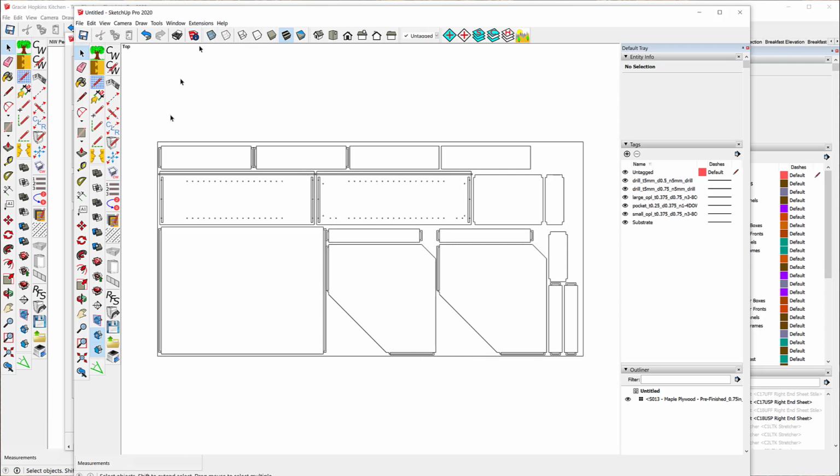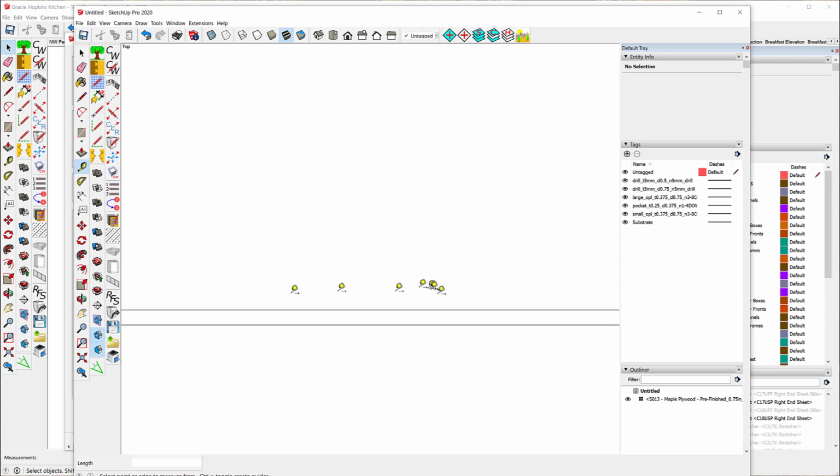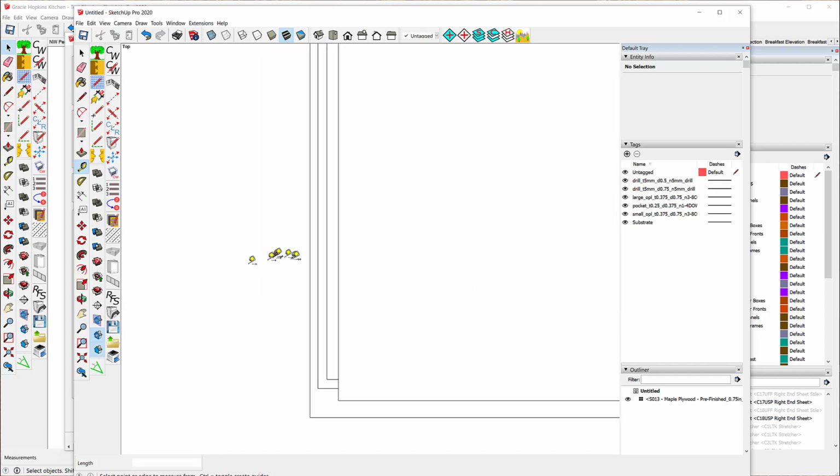Now the nice thing about opening them up here is now I can use this to measure things. I may want to make sure that the edges are what they're supposed to be. 1/2 inch, that's right. And the bottom, or the left edge. Now this is the line where the bit is going to follow, but this is the end of the tongue of the part. Notice that's 1/2 inch. And notice now that the center of the bit is here, and it won't go off the edge because it's got 1/4 inch when all it needs is 3/16.